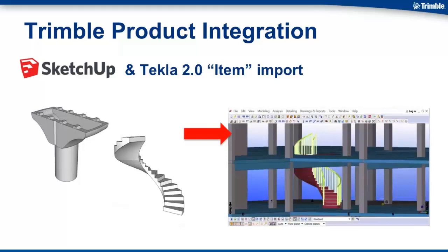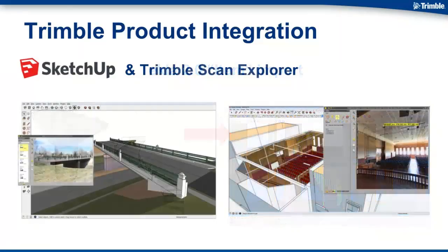Another one that has come up recently with the latest version of Tekla is you are now able to actually take SketchUp models, develop some of those hard to produce items, and actually import them directly into Tekla and actually get the valuable calculations that you might need, let it be rebar or volume calculations. And then another recent extension to SketchUp is something called Scan Explorer, which along with a RealWorks project, you're able to actually extract points of information from a point cloud basically and use that information in SketchUp to build a 3D model from.